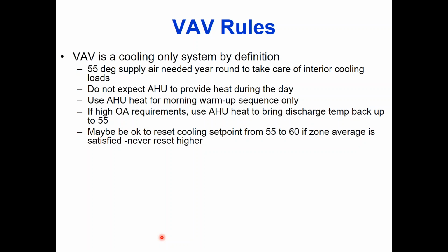No heat from the air handler during the daytime. He does his morning warm-up, and then that's it. There is sometimes that we might have the air handler heat the air up to 55 degrees, which sounds weird as heck. But if you have really high outside air requirements, we can design the air handler or the rooftop, like I showed in the last drawing, to provide some tempering to get you back up to 55, because you're going to have a bunch of 0-degree air being sucked in. So we can temper it back up to 55.